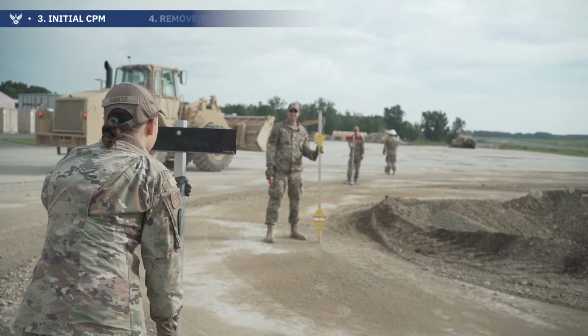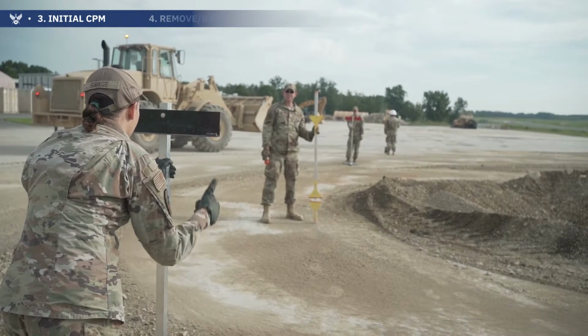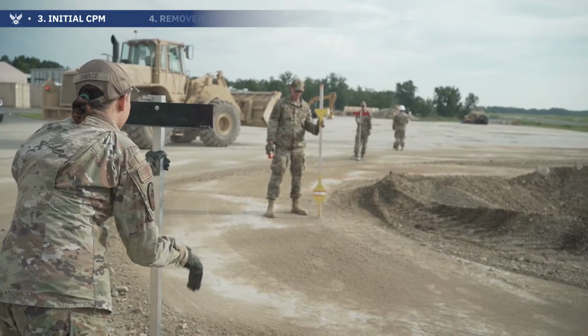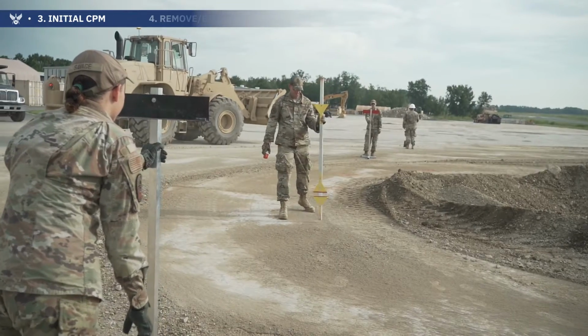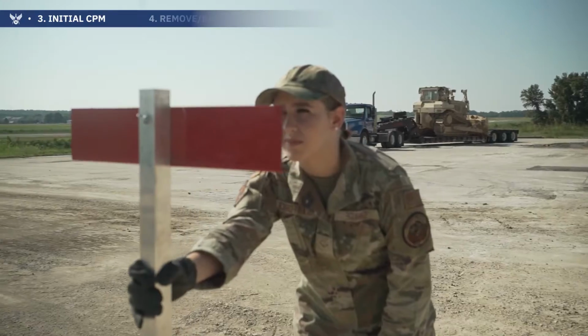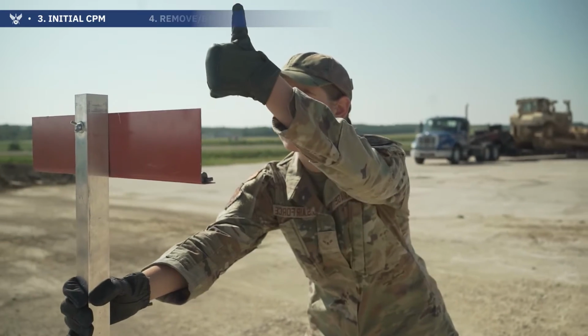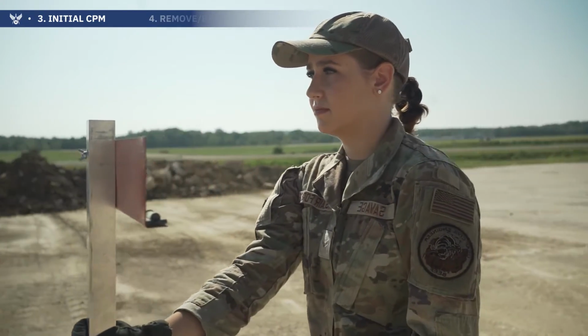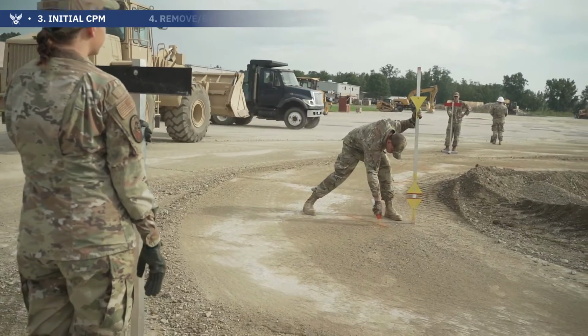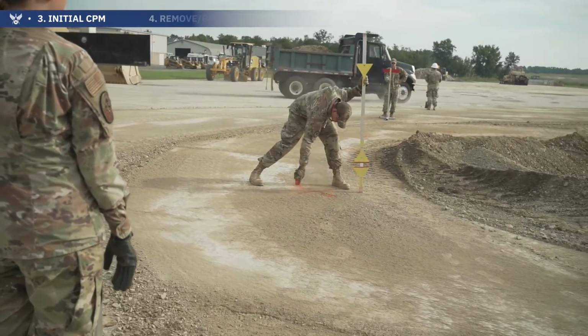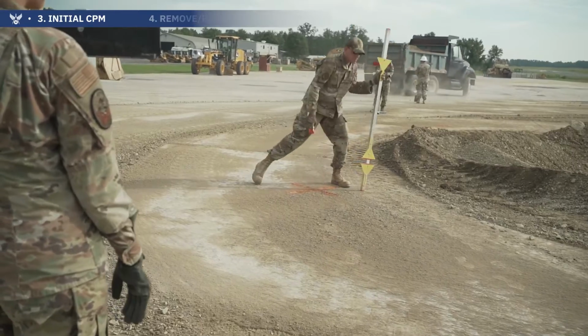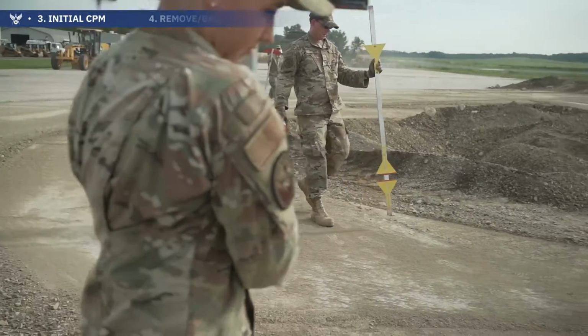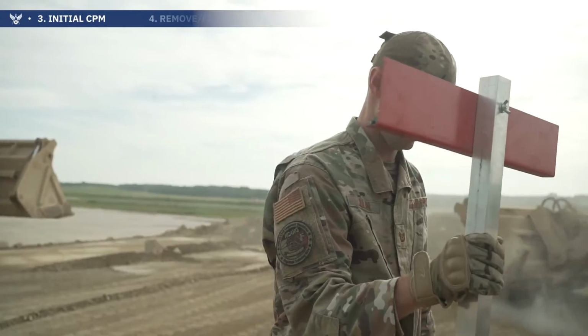Start measurements on obvious upheaval, moving away from the crater towards stanchions. Place rod between stanchion with single target out. Sight the target along the upper edge of both stanchions by standing approximately 2 paces behind stanchions. Move the rod along line of sight between stanchions. Keep the rod plumb and place on the pavement every 2 to 3 feet.